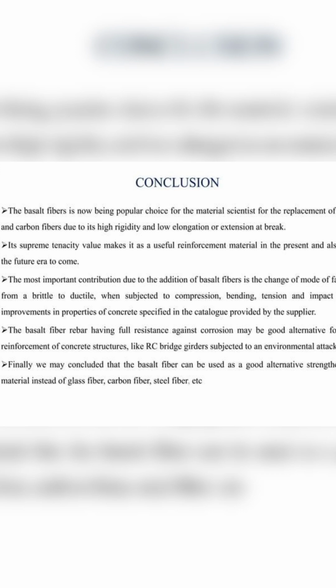The most important contribution due to the addition of basalt fibers is the change of mode of failure from brittle to ductile when subjected to compression, bending, torsion, and impact, with the improvements in properties of concrete specified in the catalog provided by the supplier. The basalt fiber rebar having full resistance against corrosion may be a good alternative for the reinforcement of concrete structures like RC bridge girders subjected to environmental attack.